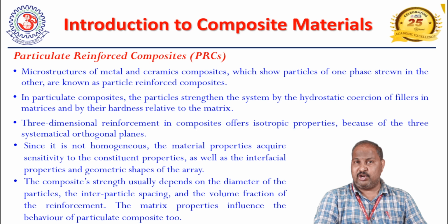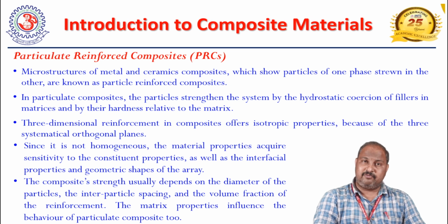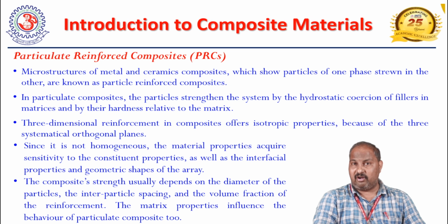It may be inorganic particles, or some compounds added in the form of particles, which are known as particle reinforced composites. In particulate reinforced composites, particles strengthen the system by hydrostatic cohesion of fillers in the matrix and by their hardness relative to the matrix. Three-dimensional reinforcements in composites offer isotropic properties compared to fibers, which are orthotropic along the orthogonal planes.